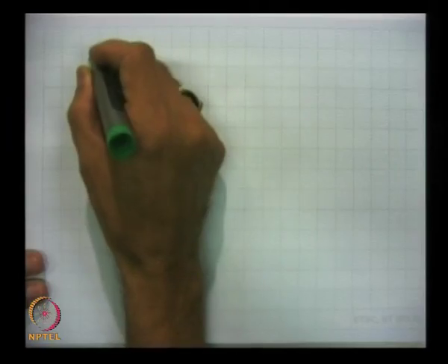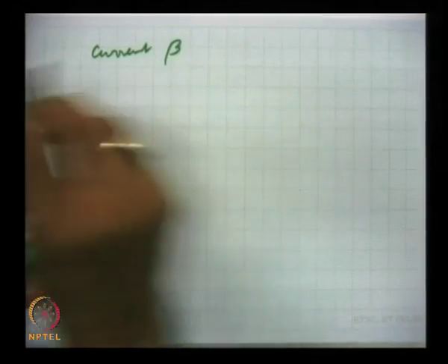Now, as we have said that in power amplifiers large swings of currents and voltages will be required, and in which the whole active area of the IV characteristics, for example, the collector characteristics of the BJT transistors, almost the whole area will be used, and the whole area means that there will be non-linearities involved. Therefore, the parameters which we have used in the small signal analysis, like current gain, beta, we took it linear.